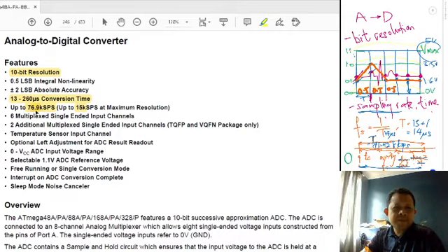So this is assuming 76.9 kilo samples per second with 8 bit. If it is 10 bit, you need more time to store. So if you go to maximum resolution at 10 bits, your sample rate goes much lower, in this case 15, because the processor needs time to store and then convert again and then store again. So you get 15 kilo samples per second.